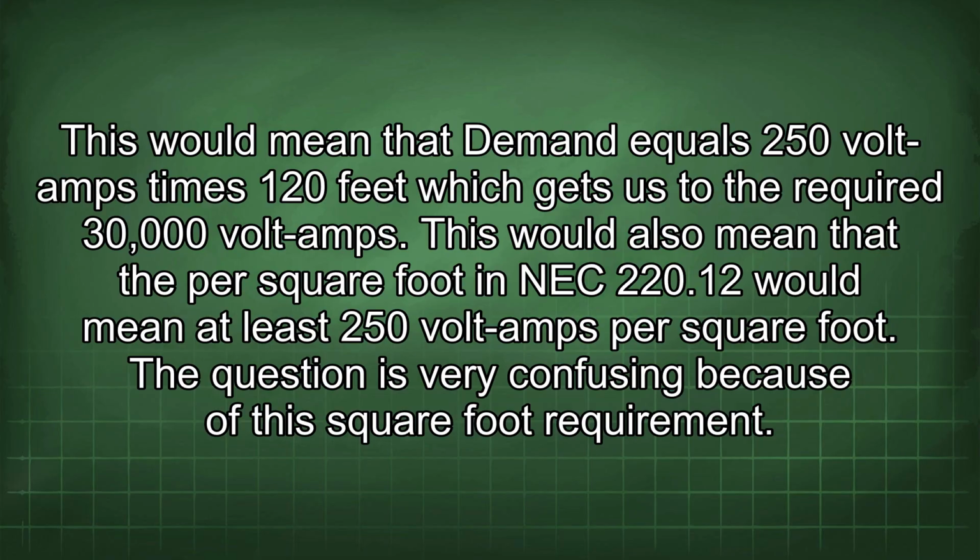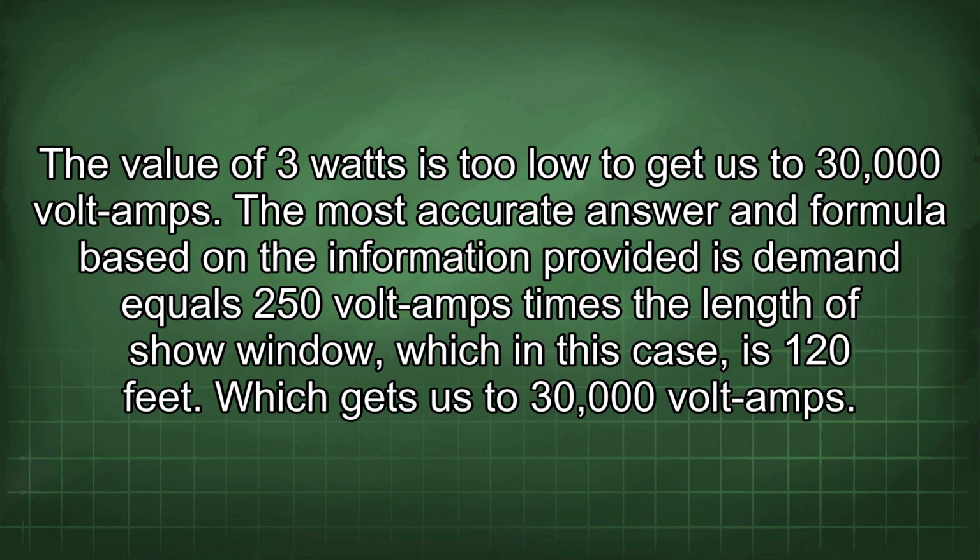This would also mean that the per square foot in NEC 220.12 would mean at least 250 volt amps per square foot. The question is very confusing because of the square foot requirement. The value of 3 watts is too low to get us to 30,000 volt amps.